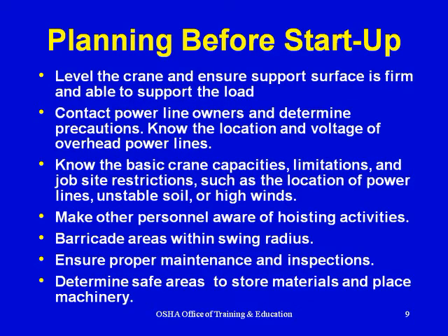Planning before startup. Level the crane and ensure support surface is firm and able to support the load. Contact power line owner and determine precautions. Know the location and voltage of overhead power lines. Know the basic crane capacities, limitations, and job site restrictions, such as the location of power lines, unstable soil, or high winds. Make other personnel aware of hoisting activities.